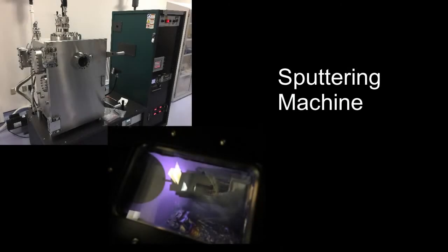A sputtering machine deposits material by creating a gaseous plasma and then accelerating ions into the target material. This in turn ejects the material, causing it to accumulate on the cell above. An E-beam evaporation machine utilizes an intense electron beam, steered with electric and magnetic fields to hit a source material. This vaporizes the material and causes its atoms to deposit on the cell above.